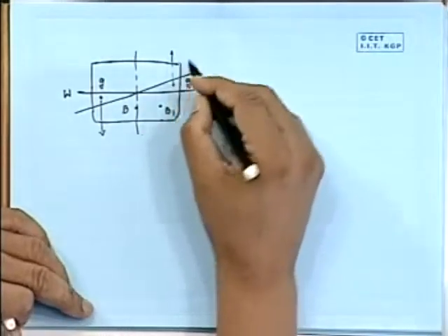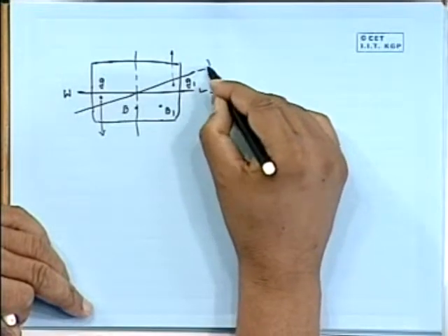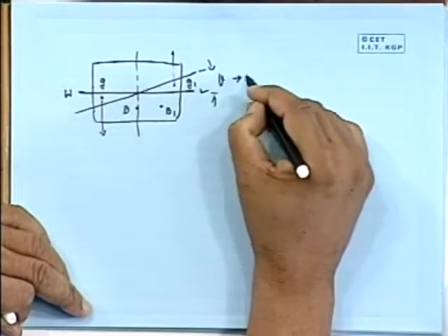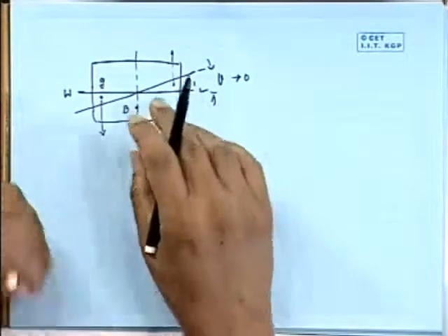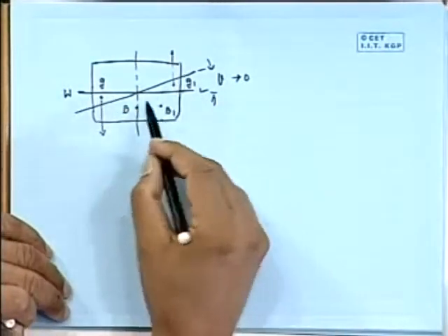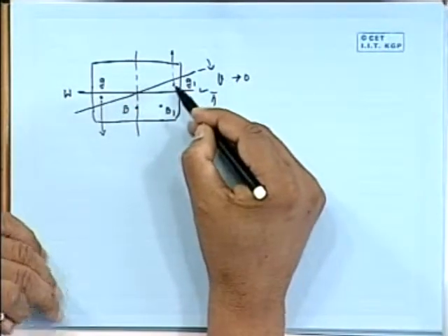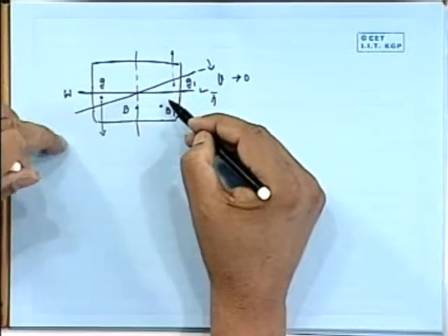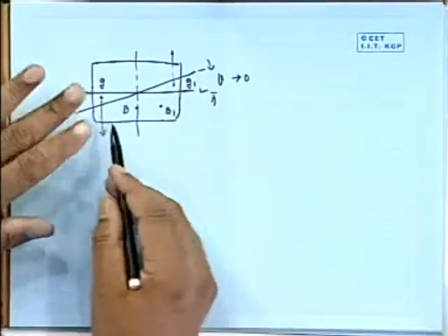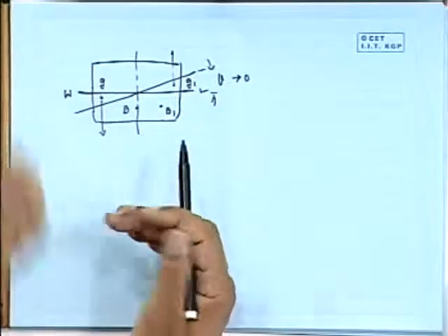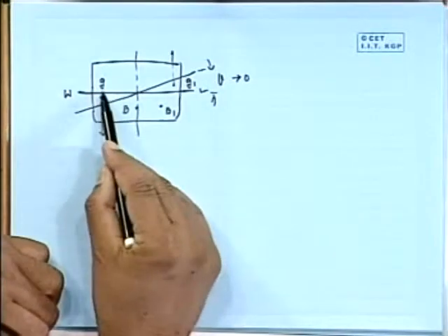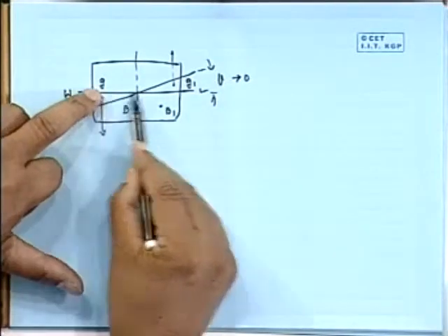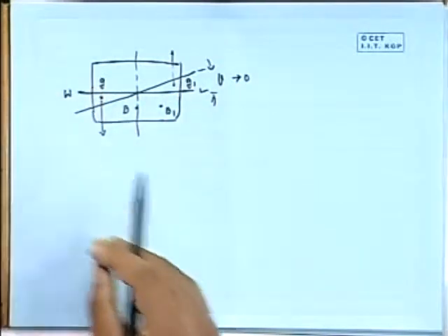But remember that we are talking of a case when theta is tending to 0. When you make theta very small, there will be no rise of G to G1. This is another point that is deceptive in the diagrams. When I make this angle extremely small, say 0.1 degree, you will find that it is as if I am simply shifting G from here to here, just horizontally translating it. There is no rise.